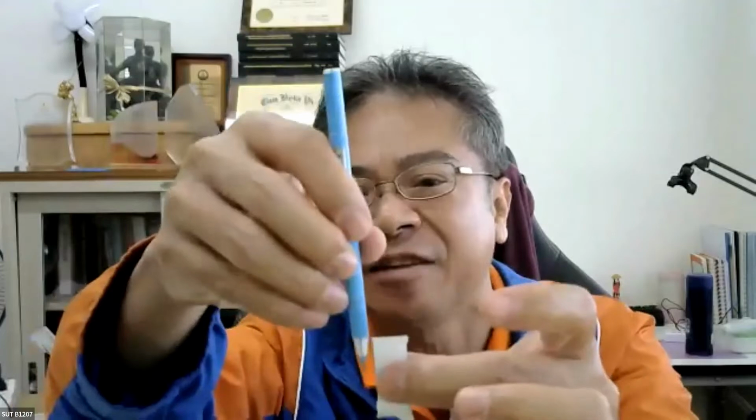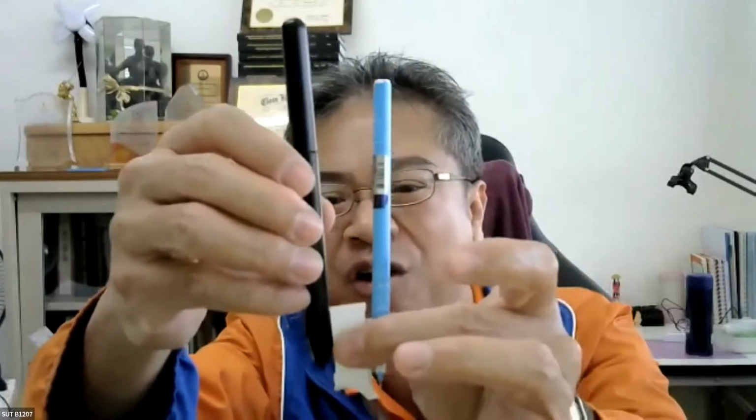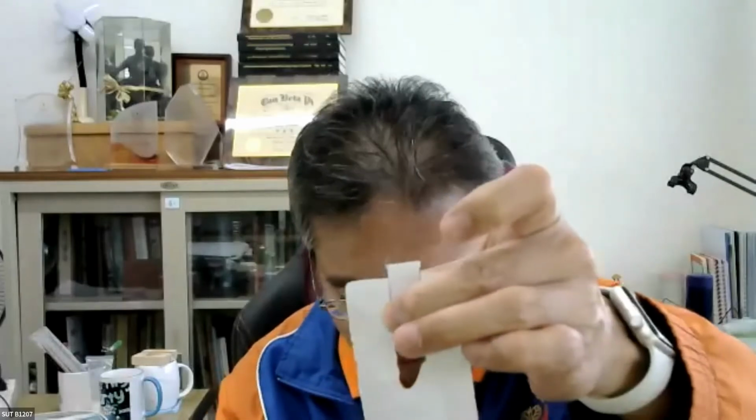Okay, we may have the force pushed into this. And since there are two surfaces, the shear force, for example, if this is 10 kilonewton, the shear force on each of the two sides is going to be 5 kilonewton. And then you divide 5 kilonewton by the area here. You get the shear stress. And large shear stress also causes the failure of the material. And I should show you the failures of these are different. The failure over here is due to the normal stress. The failure over here is due to the shear stress.